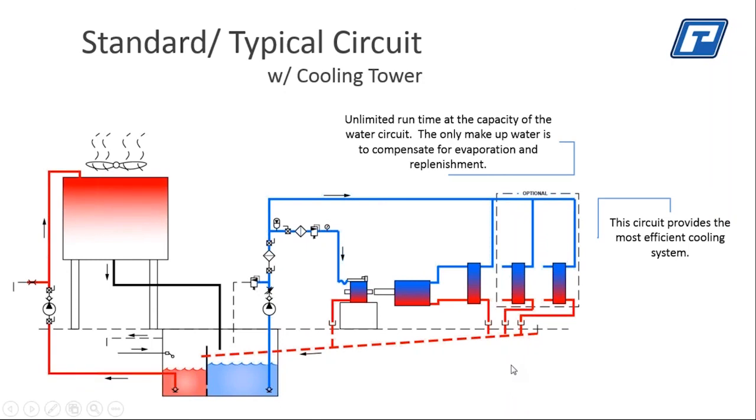Now we're going to continue on with the cooling tower. What's happening now is the hot water is being pulled up by this pump system here, and is being discharged into the top of the cooling tower. What happens is, as the fan is rotating and through the miracle of the heat of evaporation process, or cooling of evaporation process, the water is cooled and is gravity drained back to the cold side of the system. I'm hoping everybody can follow this. This is probably a very simple and smart method of seeing how these systems function. So I hope this is helpful.